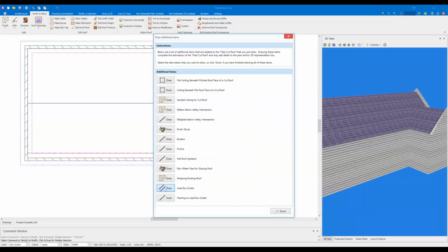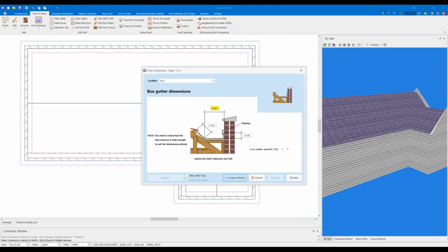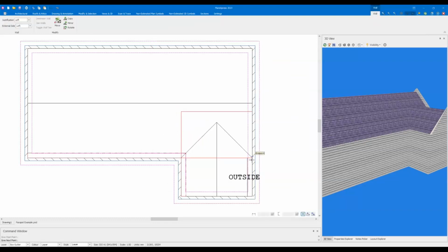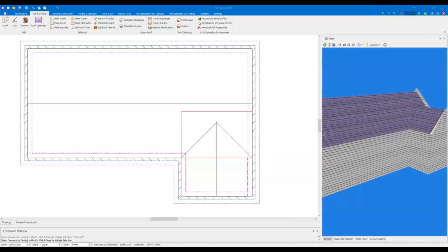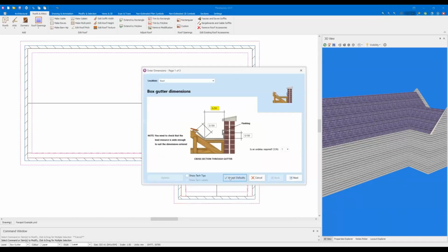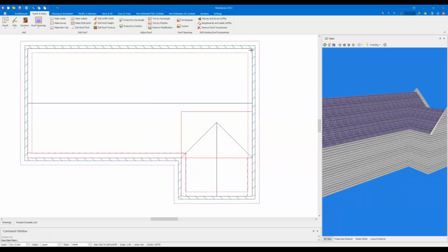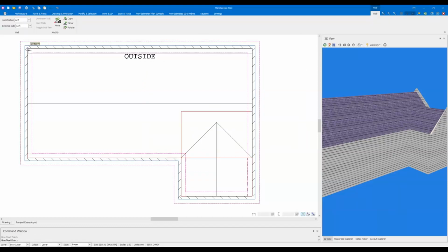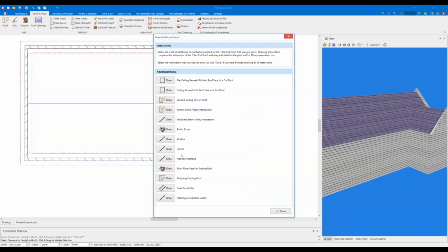So I'll go in again, another section, draw it there, and finally once more, and I'll put that along the back of the building where I've got my eaves parapet there. For completeness, I should go through and draw in flashing on the same lengths, but I'm going to skip that for now.